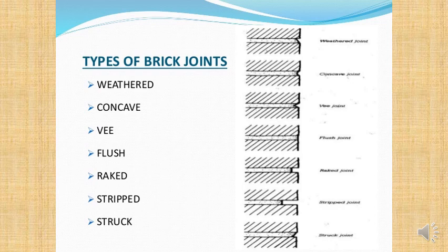So with old buildings, when you do inspections, one of the key things you would do is check to make sure you don't have gaps forming in between the blocks because the mortar is wearing away. Using a depth meter, you would probe to see how deep the mortar is, and ideally you don't want it any deeper than about 5 millimeters.